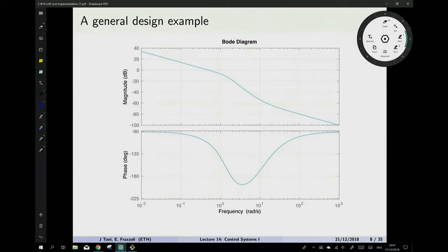We said yes, right? We saw directly from the poles that the system was stable. If we wanted to see it here from the diagram, we would look at the crossover frequency, that point there, when we cross 0 dBs. The phase there is bigger than minus 180, which means the margin of phase is positive. We're good, system is stable. Okay, so we want to make sure that after we did all our controller, the system is still stable. The requirements ask for the closed loop system to be stable, not the open loop one, right?